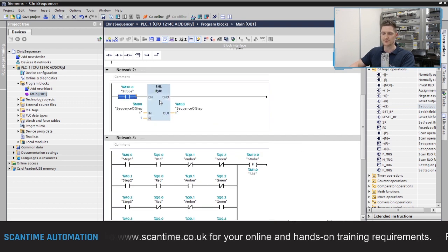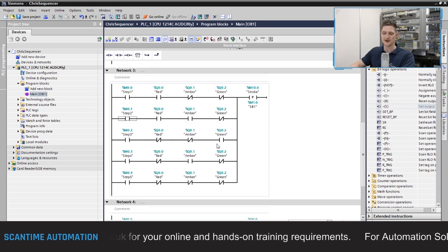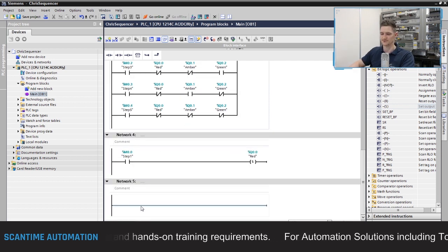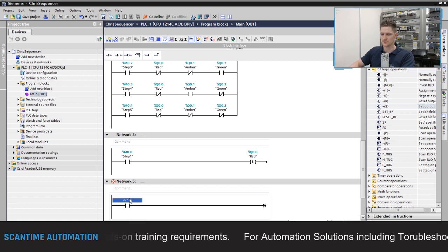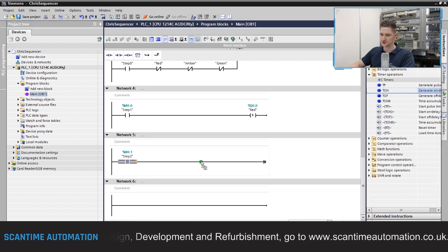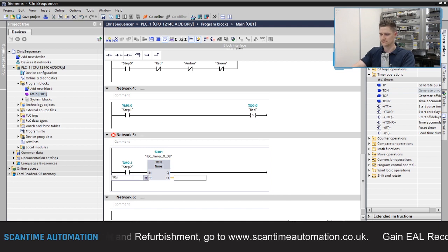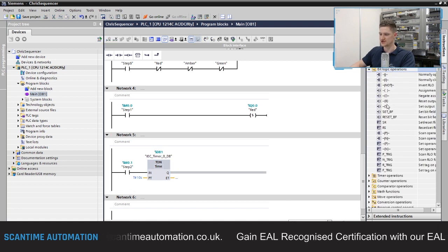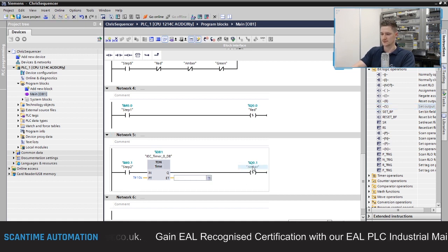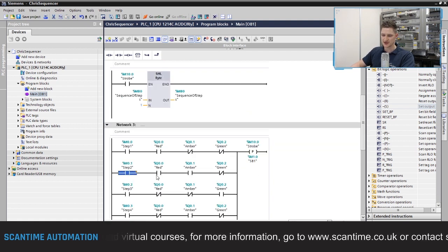The strobe signal will trigger up here, moving the bit one place to the left, turning on step 2, and then the red lamp will be on, and now we're just waiting for our amber lamp to turn on after a period of time, we'll just say 10 seconds. So here, we'll type in M0.1, step 2, and here what I want to do is run a timer for 10 seconds first of all. And then after 10 seconds, we then want to set the amber. Like that.